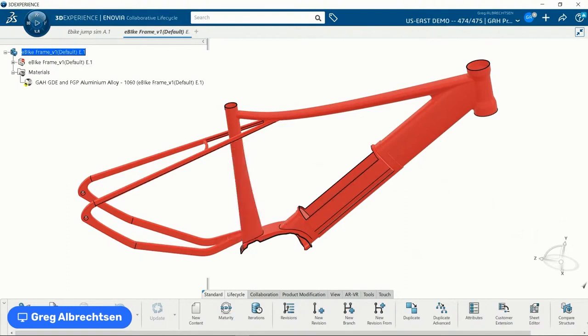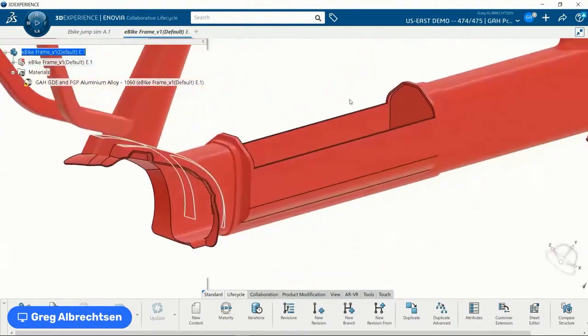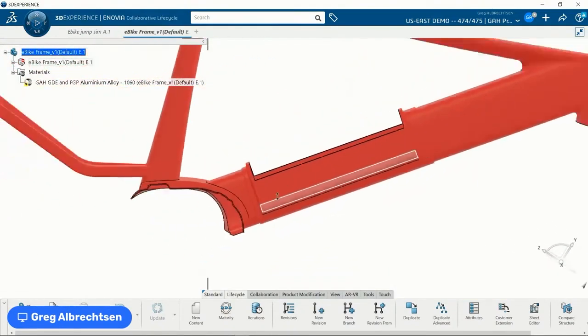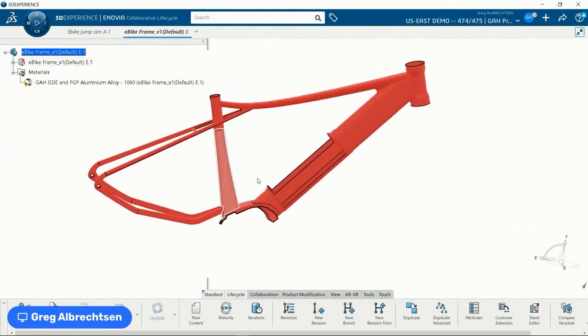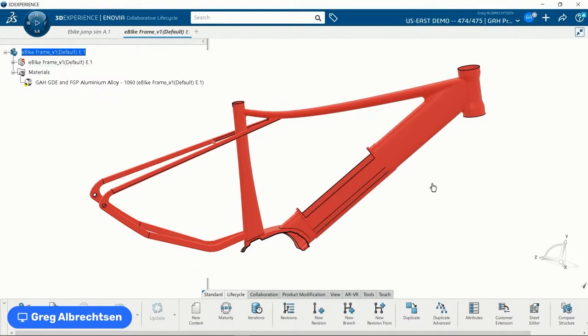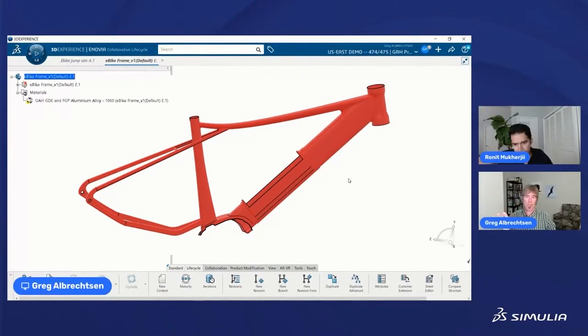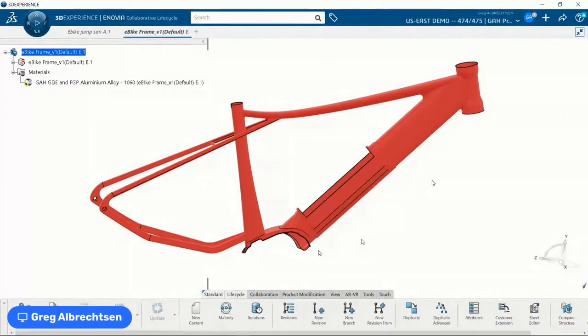So let me shell mesh the whole thing. Well, if I think about shell meshing this whole thing, this is an e-bike, and here I have my battery compartment, right? That's kind of a big, solid, chunky block. So if I was to shell mesh this whole thing, what happens with this section here? So that wouldn't be a good approach for this section. Correct. So what do I do? Well, we have the capability to create a mixed mode mesh. And what I'm going to do is go through and show you how I can shell mesh and solid mesh this single part.